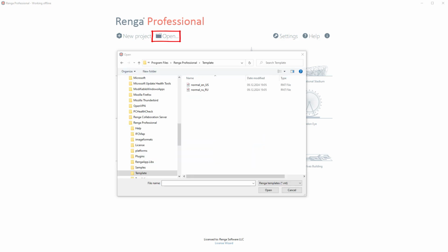You may open projects that were created not only with Renga application but also with third-party ones. The following formats are supported: Renga File RNP, Renga Templates RNT, Industry Foundation Classes IFC. It is recommended to always create a new project from a template where there are lists of prepared properties, styles and materials. For that, on the list of file extensions, select the Renga Templates option.